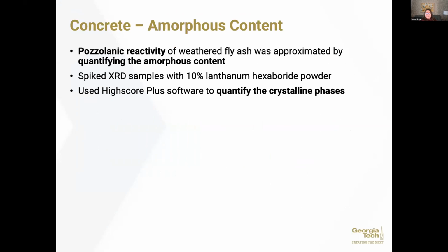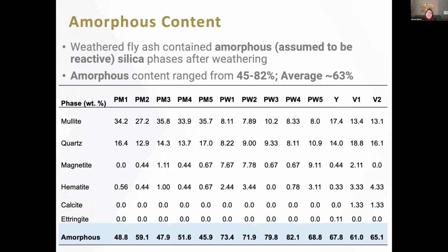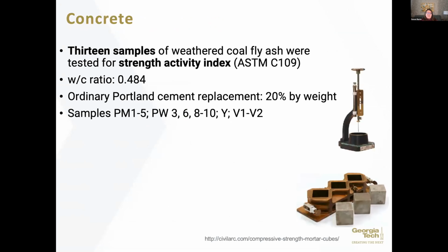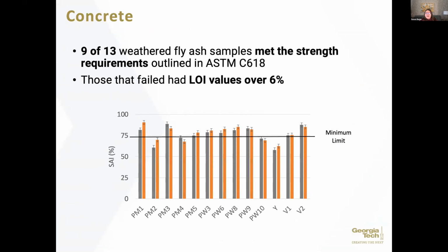In concrete, we also have to worry about the amorphous content, okay? And so we know that that's the surrogate for pozzolanic reactivity. And so we came in and we measured that amorphous content. You can see the silica hump that we have here using XRD. And in all of these cases for the ponded ash, we saw a reasonable amount of amorphous content too. So what that's going to tell us, when we test the strength of these ashes, is that we get reasonable performance in terms of the concrete that we made out of these ashes.